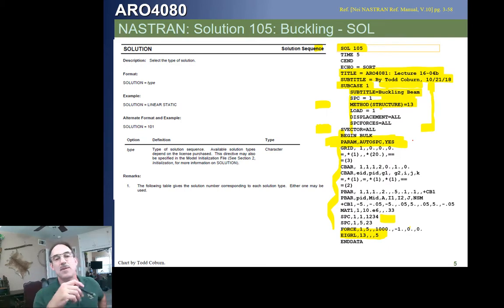This is useful. Let's say we have a two-dimensional model and we calculate all of our nodes and properties in this plane and we don't restrain it out of plane. Now some of you are starting to get sharp and you're learning to constrain the third degree of freedom. We put a 3 in for each and every node, which keeps it from moving that way. If we hadn't done that, the model would be singular and would not probably run.